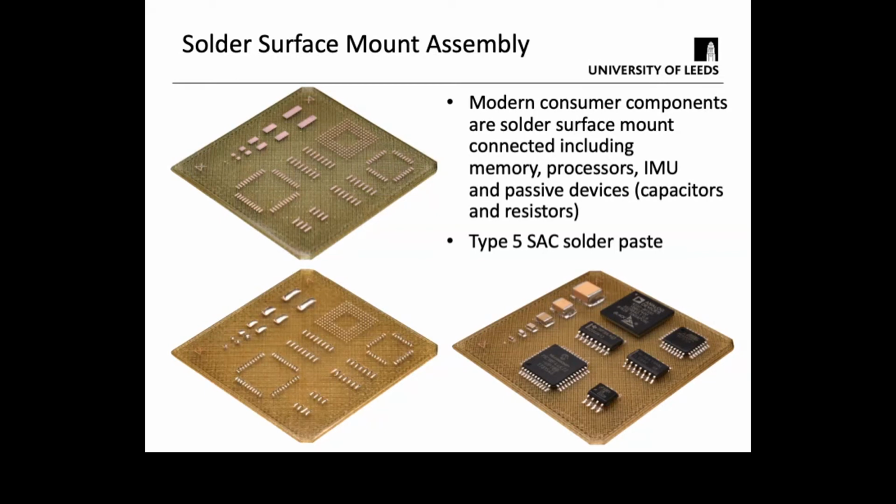If you look at the way that the electronics industry do their testing, what I'd ideally like to see going forward is that we do some sort of thermal cycling, accelerated age testing. I'd like to see what they call daisy chain connections, so we can interrogate electrically the devices, and use other kinds of reliability testing, like shear testing or drop testing, to ensure that this technique has benefits to the industry.